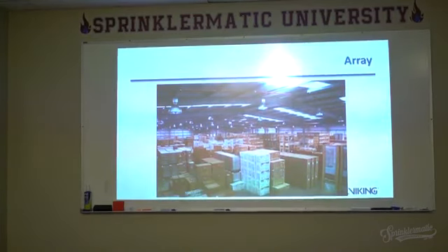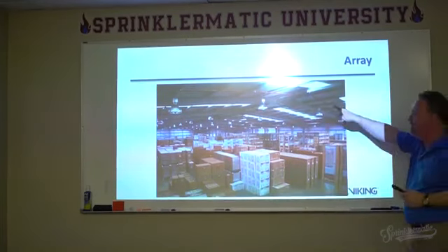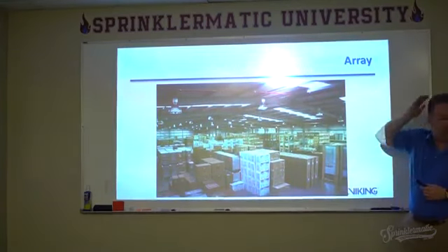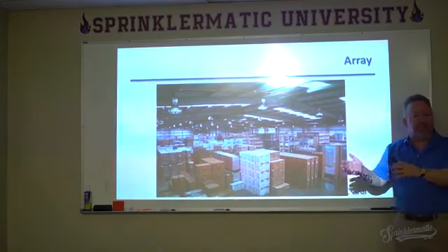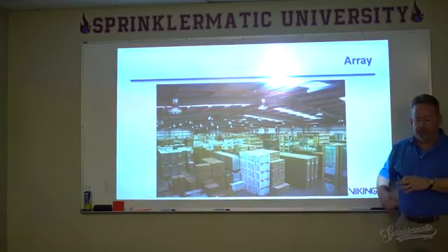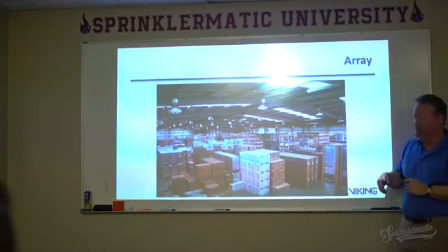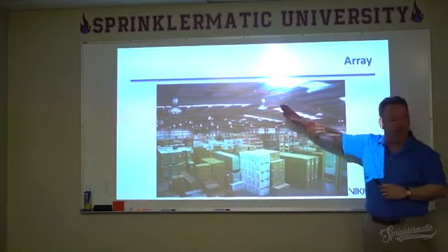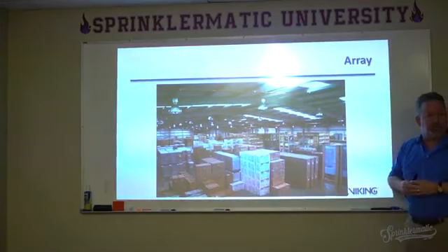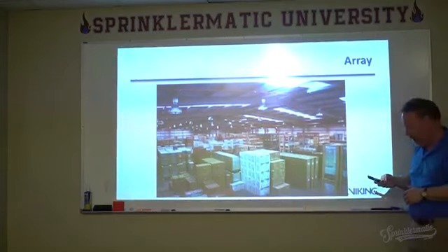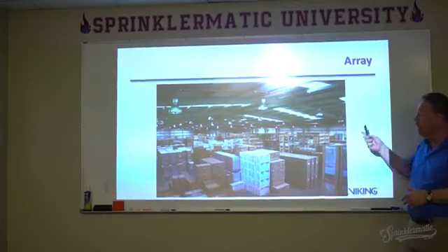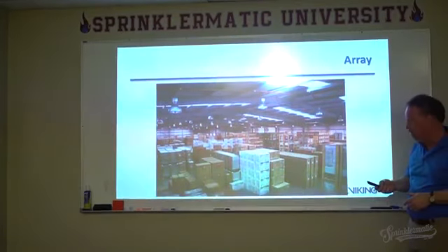Is it going to be a really tightly packed pile, or is it going to be an open pile? Because that does have an impact when we get into chapter 14 or chapter 16 in the storage requirements for the protection arrangement. It does have an impact on the overall design densities for protection of that storage.